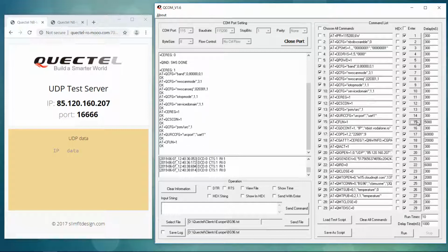Now turn on the module and set the APN. This value is very important for the device to work. So APN is something you can get from the operator, specific to each operator. Next one, execute manual registration to Vodafone Romania on 9, which means NB1 network. So the module is already registered. We got OK here. It may take some time until you get OK, so don't execute other commands until you have an OK here.